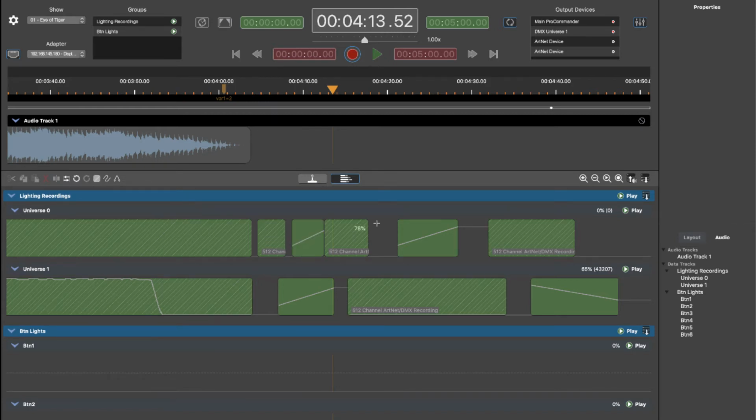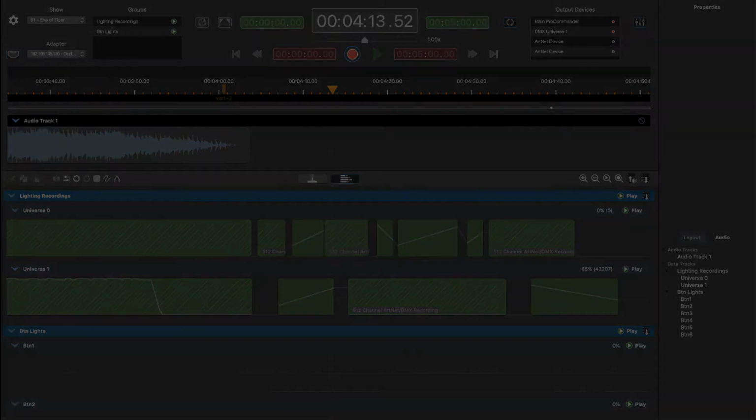For drawing, I can insert a drawing envelope in between envelopes and control all 512 or all group channels at one level. This is great for fade outs, fading things up to full, or testing and adjusting, or maintenance shows. It is not really designed for practical applications in show editing. This should be done with this track mode in the lighting console and brought into Showforge as a block of data to be repurposed, trimmed, edited, and then of course exported.